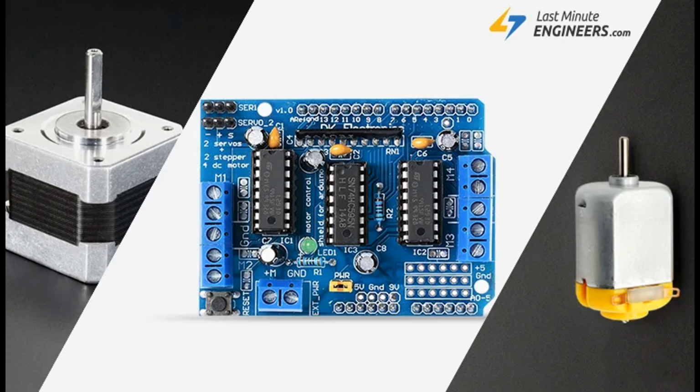3. Closed-loop servo drivers, feedback-based. Function: closed-loop servo drivers combine feedback mechanisms, usually encoders or resolvers, with the motor's control system to continuously monitor the motor's position and make adjustments in real time. Operation: these drivers ensure that the motor maintains its position, speed, and torque even under varying load conditions.